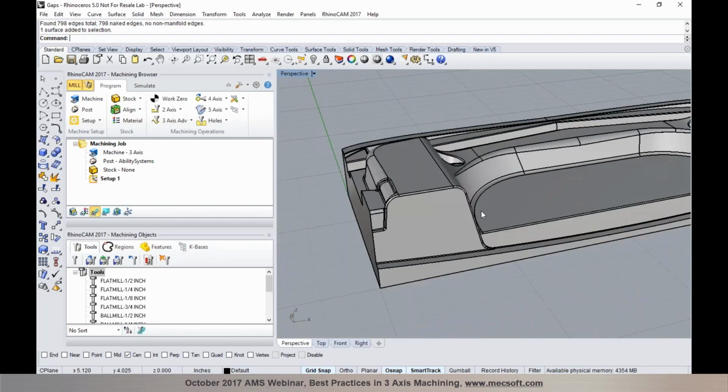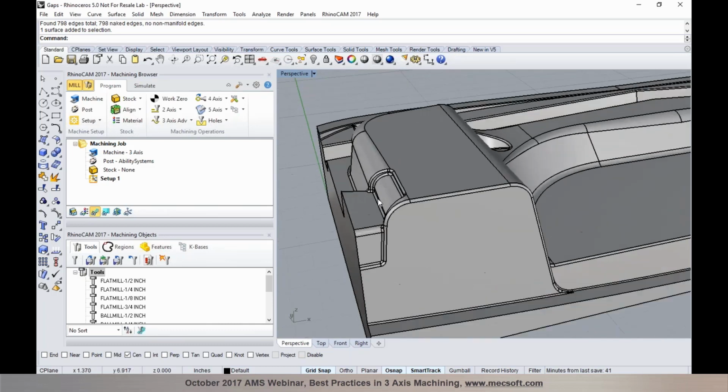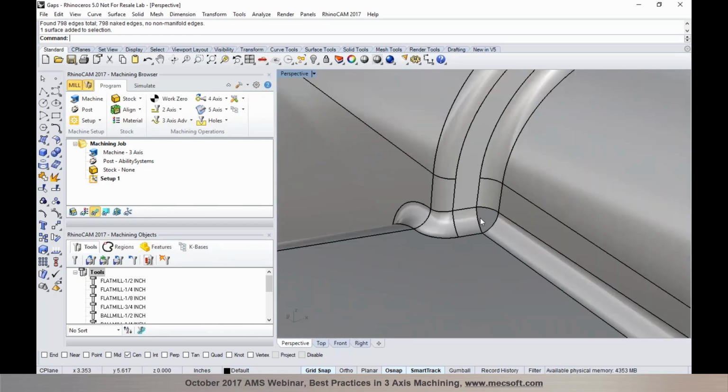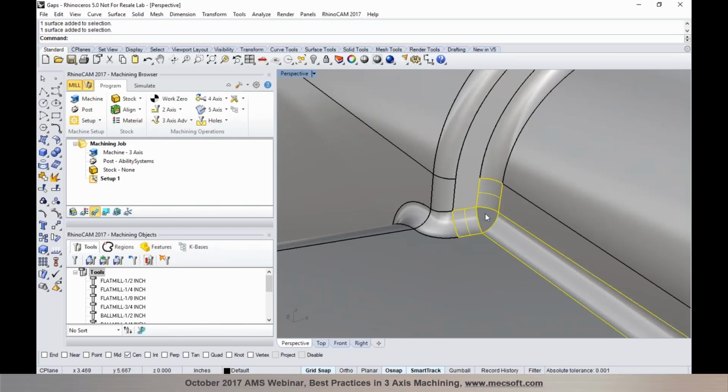So let me interrupt here, Uday. As far as the gaps, you can think of the problems associated with machining. When you have such a large gap, like a fillet or an end fillet missing, the danger is it's so tiny that you miss it and run the machining operation. The machining operation will work fine, but if you're using a small enough tool, the tool could potentially go into that hole and down to the bottom surface. That's your catastrophic or pathological case.